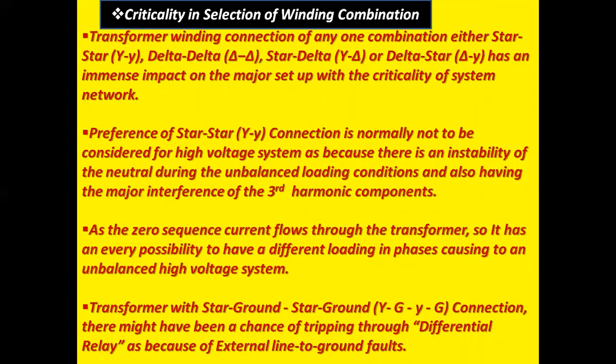Criticality in selection of winding combination. Transformer winding connection of any one combination, either star-star, delta-delta, star-delta, or delta-star, has an immense impact on the major setup with the criticality of system network. Preference of star-star connection is normally not to be considered for higher voltage system. Again, I repeat, preference of star-star connection is normally not to be considered for higher voltage system,